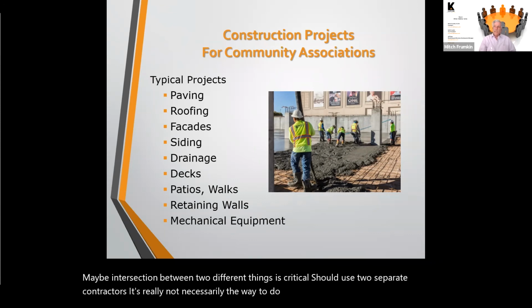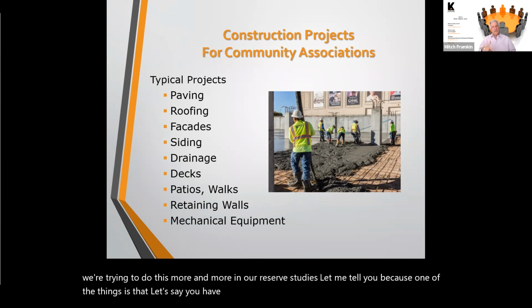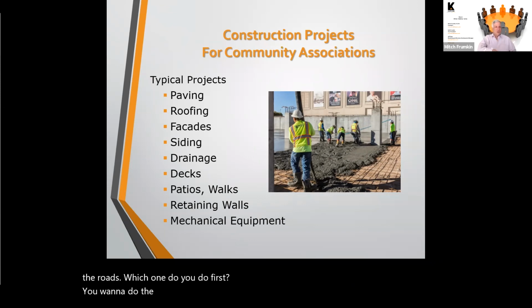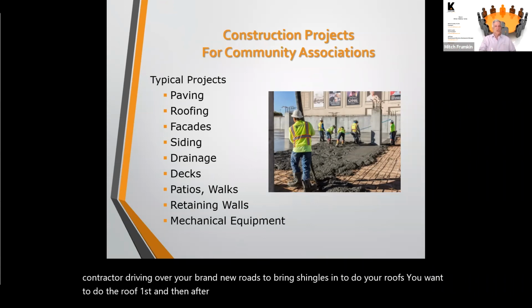The other thing is that strategically, and we're trying to do this more and more in our reserve studies, let's say you have a community that's going to do the roofs and then do the roads. Which one do you do first? You want to do the roofs first because you don't want to do the roads and then have a contractor driving over your brand new roads to bring shingles in to do your roofs. You want to do the roofs first, and then after the roofs are done, start doing the roads, so you're not destroying the roads by doing the roofs.